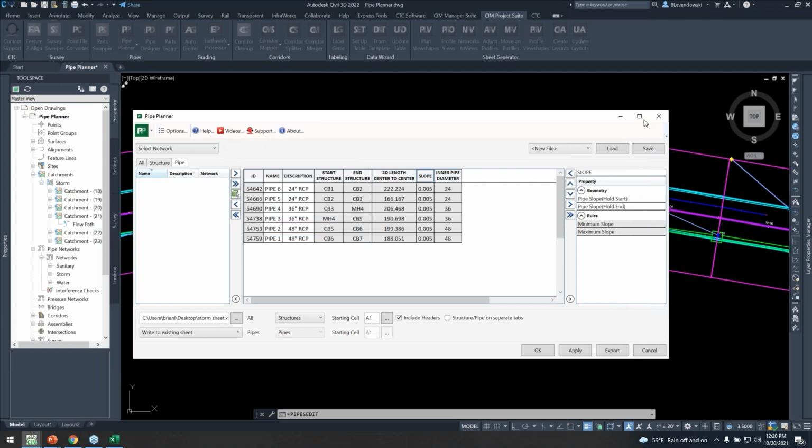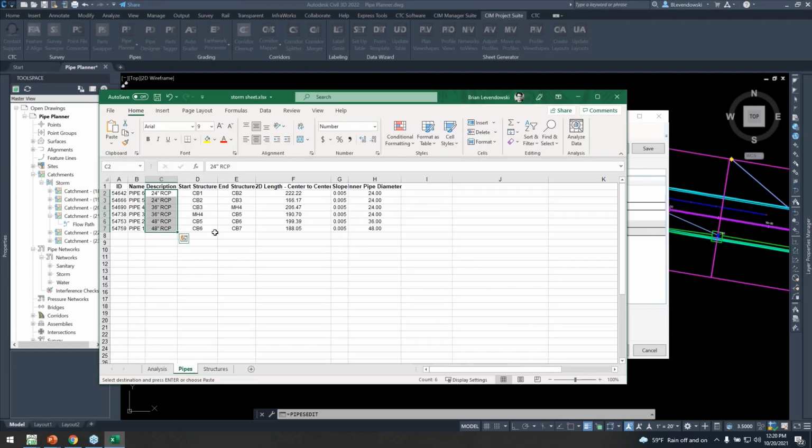When we come back and we import this, it's going to look at the description, and if the description changed, it will change the part, not just the description of the part, but it will do a swap part. So the key link between automating the pipe size changes in here is to make sure the description has been updated in here. And I'm just doing this manually here, but however you want to do it, okay? Some formula trickery.